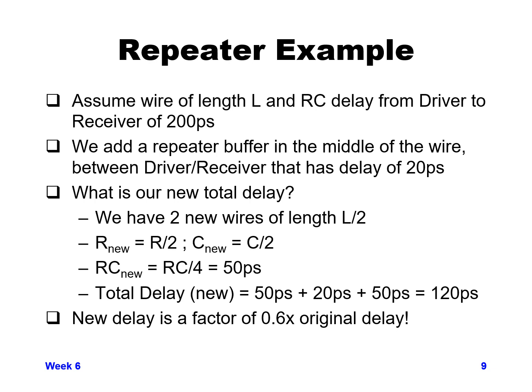So this is a really good way to get better delays out of your circuit, even though you're adding additional stages to your circuit. So keep in mind, when you get long metal wires, adding repeaters in them can actually help improve your overall timing.